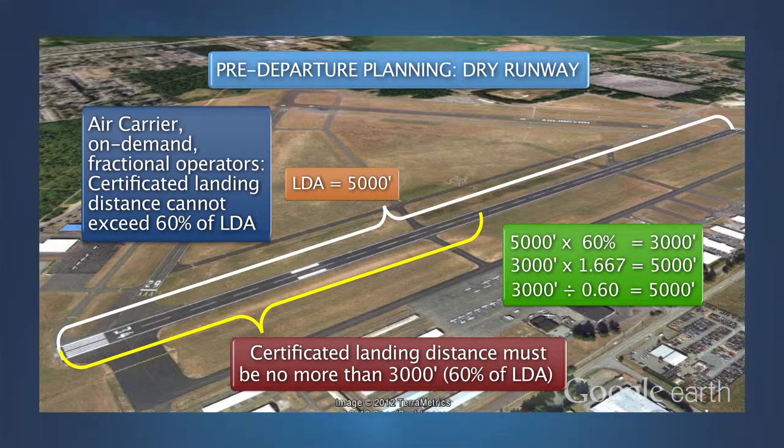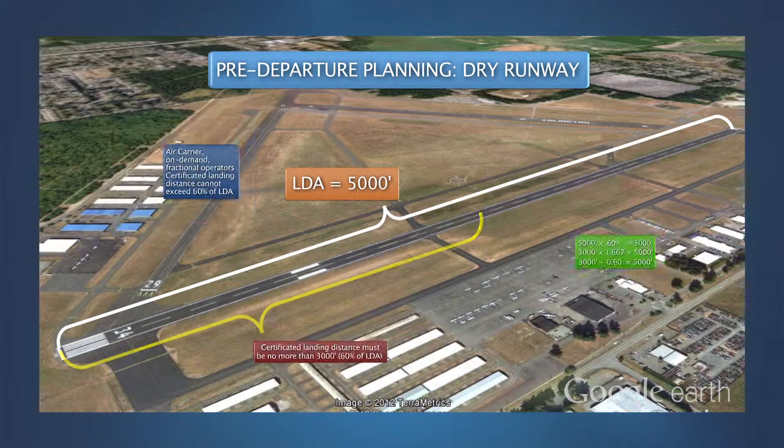The resulting factored landing distance is intended to account for operational variables, including piloting techniques, flight path deviations, tire and brake wear, atmospheric conditions, including gusts, and other variables not addressed during landing distance certification.